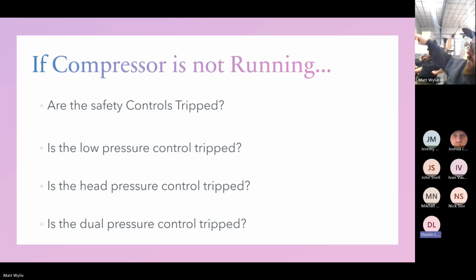So don't make the mistake of checking just to ground. You have to check across it. If you've got voltage across your switch, it's open. If you've got nothing across your switch, it's closed. But again, I only know because I made the mistake.